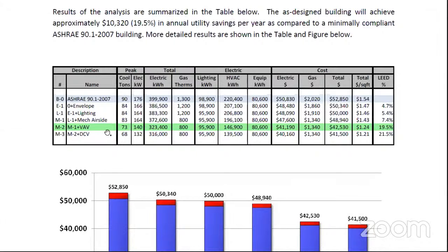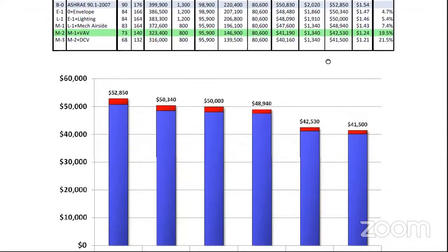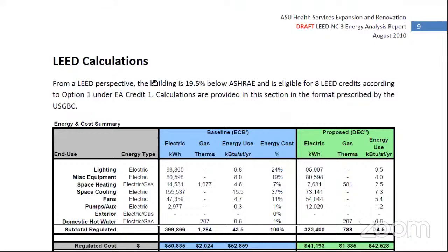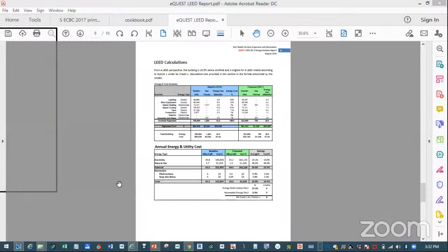When you are using demand control ventilation, the cooling capacity drops and your power consumption also reduces. So these are all ECMs that can be applied for your project. Yes, your demand control ventilation will adjust the fresh air supply based on the CO2 level.